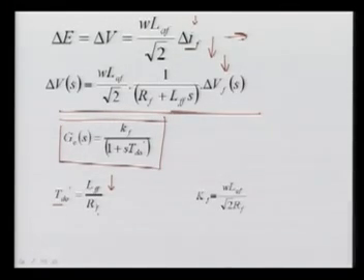If you measure the time constant while ignoring this LAF effect, then it should be with your armature open. There will be no induced current there, so we can write the time constant of the field winding as LFF upon RF. So it is TDO prime. We can represent this for your generator model, and for KF we can write omega LAF divided by root 2 RF.